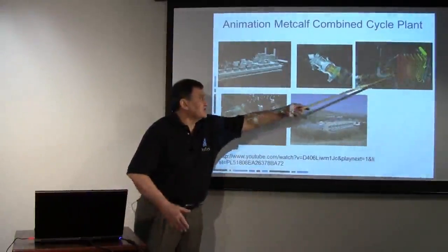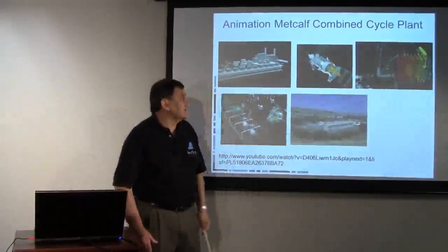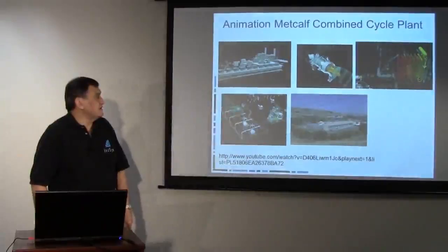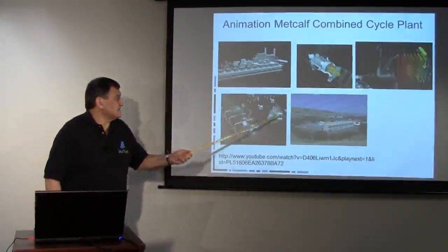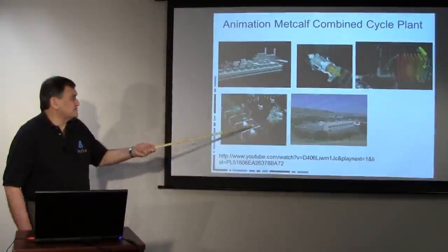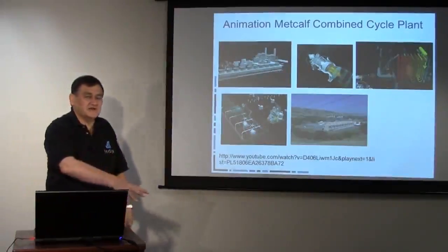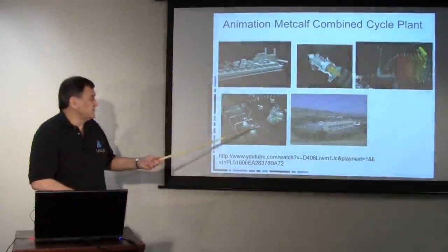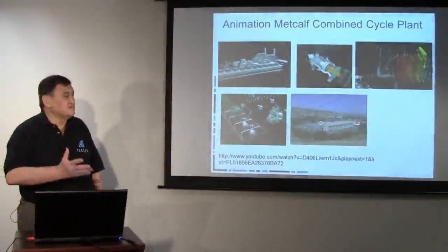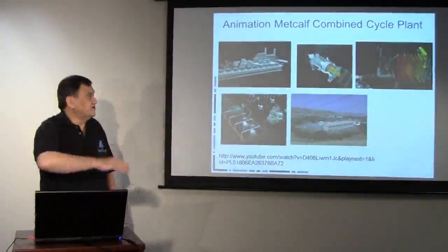And so the water coming through here is going from a cold state to hot steam coming out to drive the steam turbine. And we see the condenser taking place, and then the cooling is, in this case, actually taking place with fans, and they take that water and they blast it down like a spray, so we get the latent heat of vaporization having an additional cooling effect.